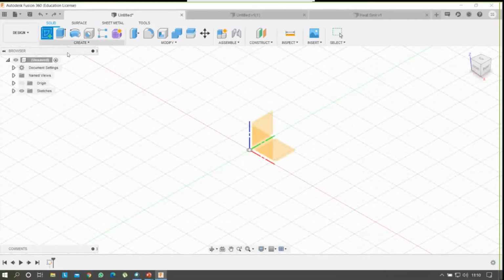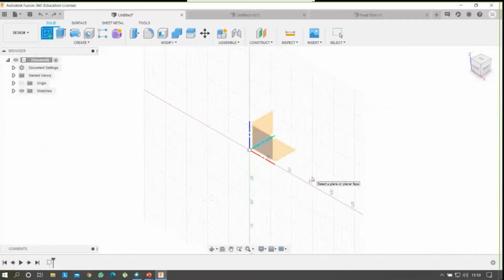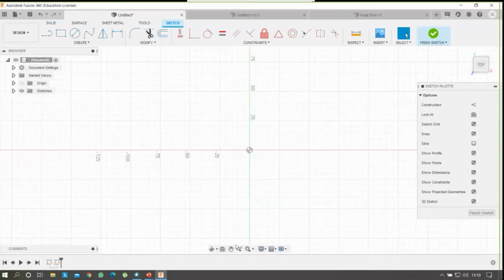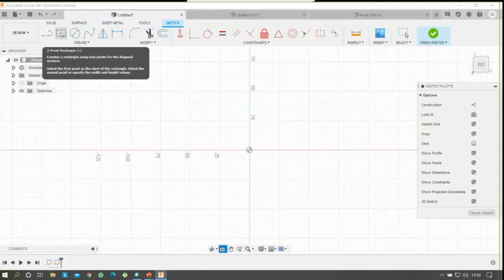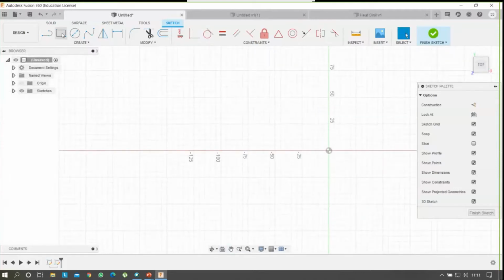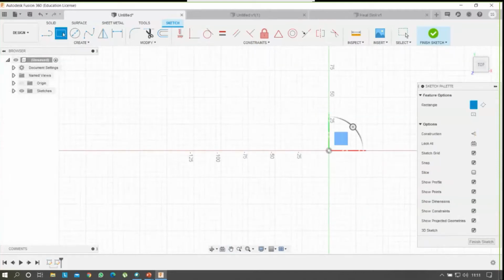So I'm going to disable this and create a sketch, selecting a plane and looking at it in the perpendicular direction by clicking on the look at direction. Okay, so we are going to make a mobile phone 2D sketch. We are going to take a rectangle first.